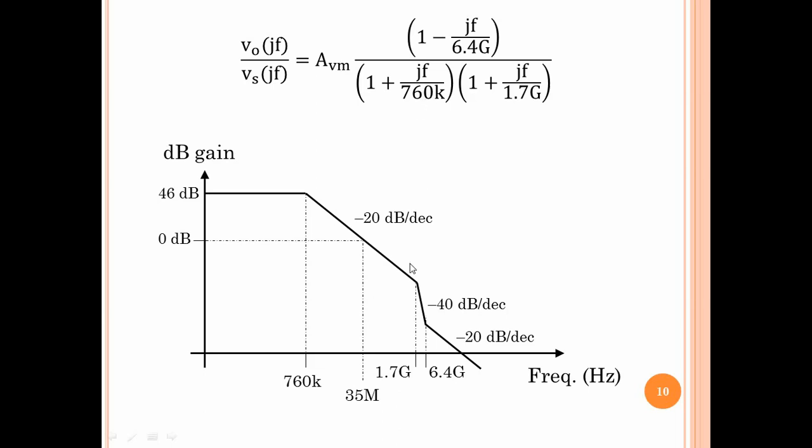But given that for our specific transfer function, the unity gain frequency occurs much before the second pole and the zero, the fact that the unity gain frequency is the product of this gain and this 3 dB bandwidth is still approximately correct, as you can see from this plot. This part of the plot is unaffected by the second pole and the zero.